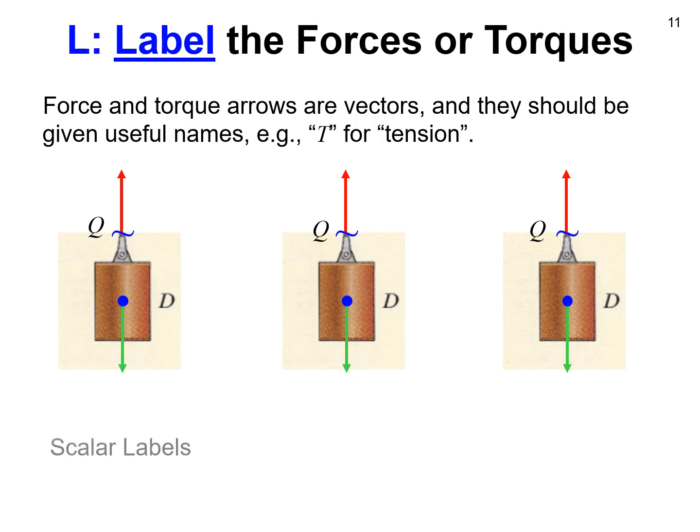So for example, let's look on the left and say we use a scalar labeling system. What I'll do, for example, is I'm going to label the force in the cable T_BD. The T might stand for tension. The BD might represent it's going between bodies B and D, so it kind of means something. But again, I'll use a scalar symbol to say that that T is the magnitude of the force represented by that arrow. In a similar way, we use mg, the mass times the gravitational constant, to represent the magnitude of the force of gravity pulling down on the cylinder.